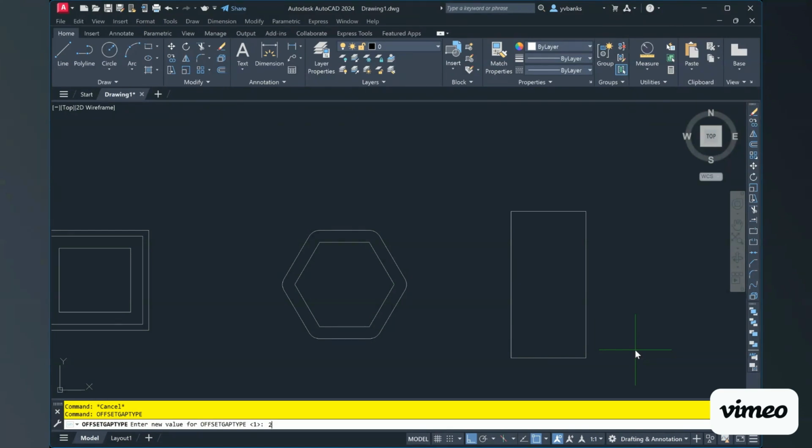When you put in a value of 2, we're going to now chamfer our line segments at their projected intersections. So now these 4 corners here will no longer be at 90-degree angles when we go to offset them. The perpendicular distance from each chamfer to its corresponding vertex on the original object is also going to be equal to the offset distance.